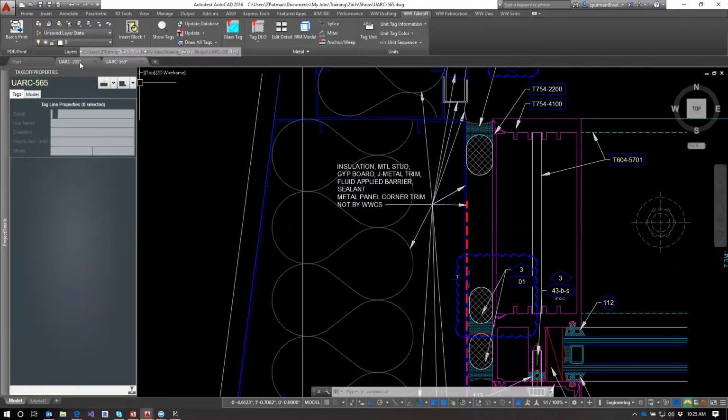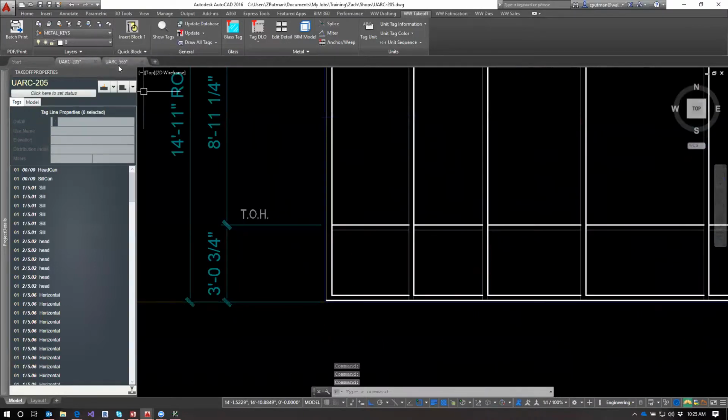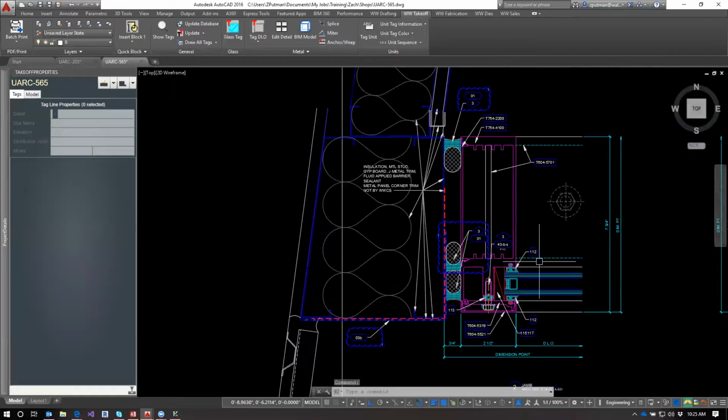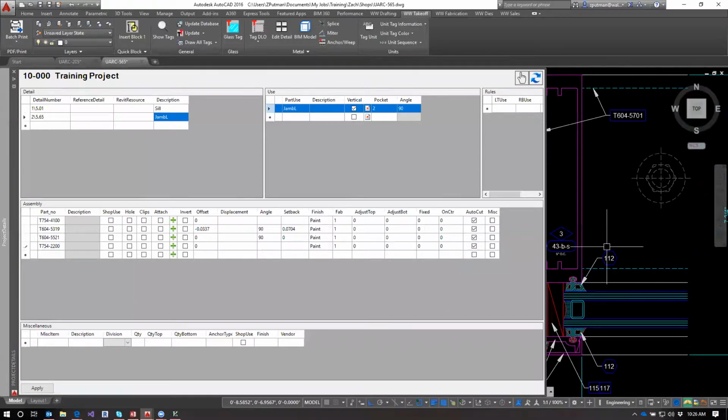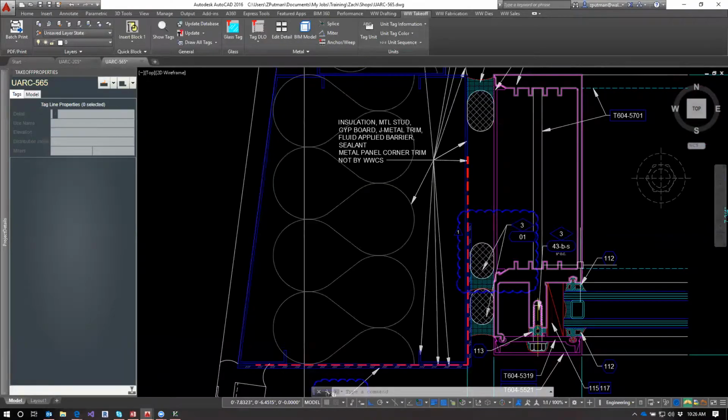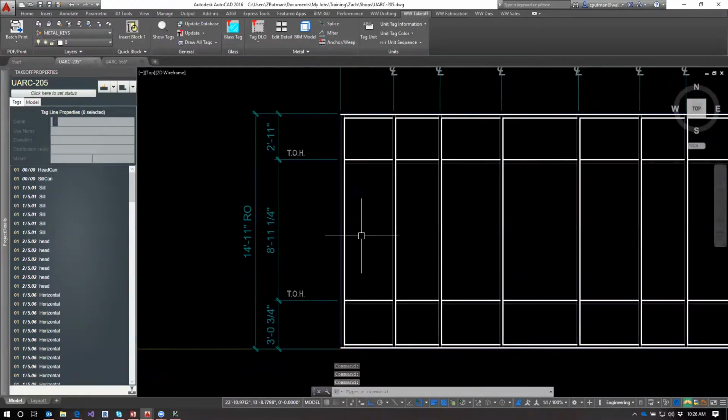I could have included the T-clip in the sill data. I could have put it in the vert data. It's interesting, you kind of have options with that. I almost don't like to put it in the actual vertical, because, at least for us in Fremont, if I put it in the jam, the mark number for the T clips or the L clips or whatever you want to call them, they go with the jam, so they'll be up here in the middle.